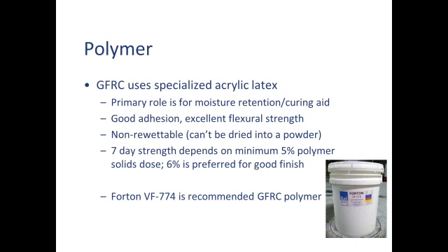When you make GFRC, it's a very specialized form of concrete that depends on it being made right with the right ingredients. That's the only way to extract the high flexural strength to be able to make very thin concrete that's resilient, crack resistant, and because it's thin, it's light. That's a very well understood industry that's been used globally for 40 years. The ingredients and all that are very, very well categorized and tested and understood.